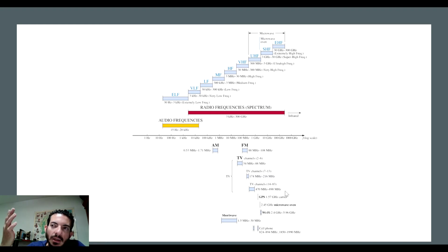Okay, so satellites are transported up to low Earth orbit, where they are capturing data, or receiving the data and then sending it back to the receiver here on Earth. They operate at 1.57 to 1.6 gigahertz. The 2.45 is the microwave oven, we just saw that. Wi-Fi is between 2.4 and 5.9 gigahertz. And the cell phone voice signal is between 800 megahertz and 1900 megahertz.